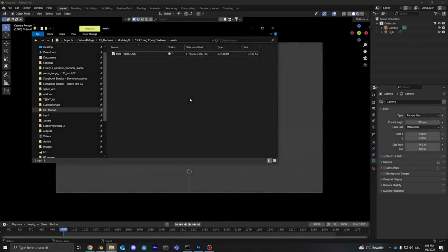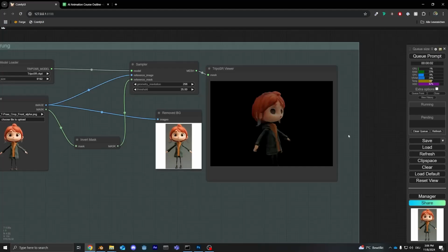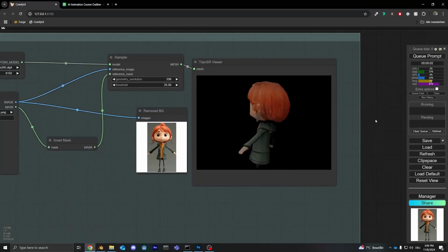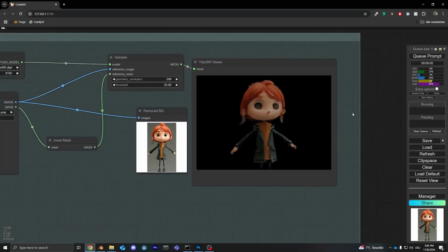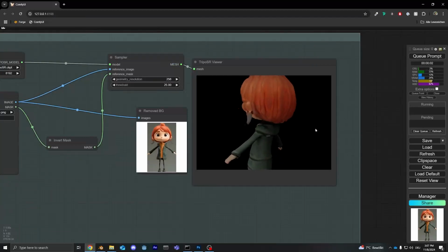In this course, we're showing you a couple different ways to get high quality textures from your AI generated 3D models. But what if the absolute worst case is happening? So you're using an old AI model like TripoSR to create your OBJ, and the textures look really bad. If you bring it into Blender and show the textures, it's not even showing textures. If you look at it in Comfy, it's really, really bad. And you're not using your own local GPU, so a tool like Stable Projector Z won't be an option for you. What can you possibly do to get a higher quality result out of your textures?